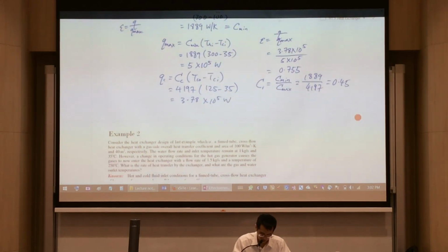And the last thing that you need would be your NTU, we represent it by just N, or writing the whole thing as NTU, equal to UA divided by C min. So what we're interested is to find out what is the NTU. And the way to figure it out is that you would have your CR and you would have your effectiveness.